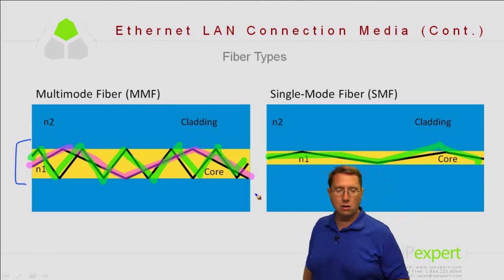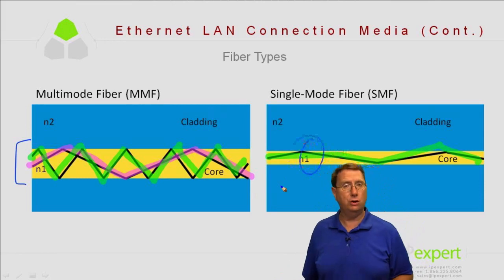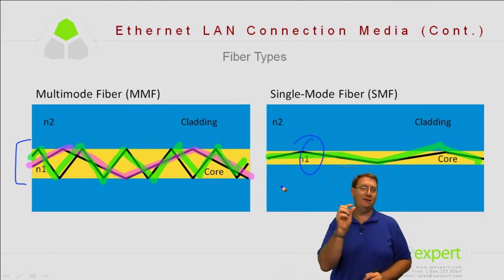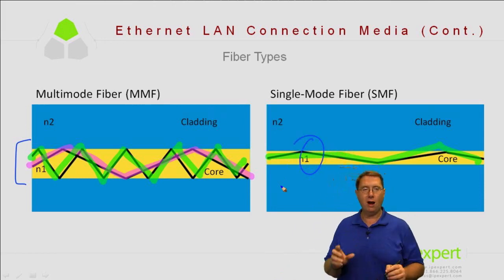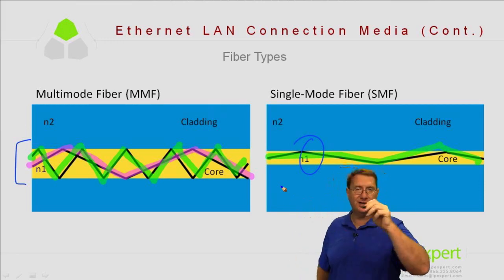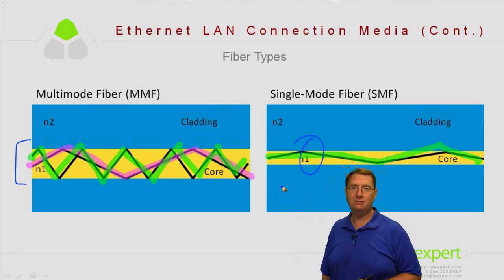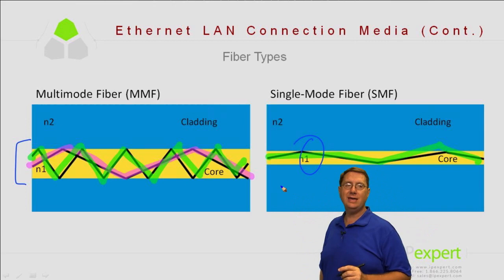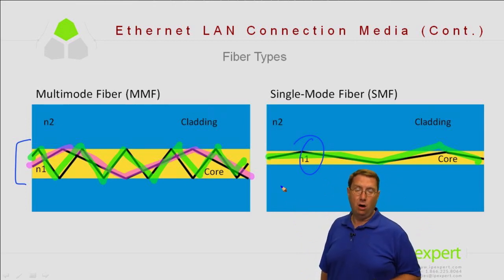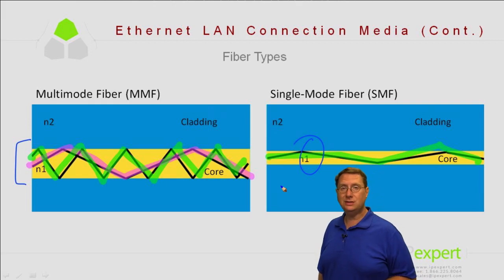Now, there's no requirement for that when we start looking at single mode fiber. So in other words, I can have a smaller conductor, therefore I'm losing less light because I have less reflection going on against the outside of the core. But when we start looking at it, I can shoot greater distances using single mode, also because I'm only carrying the one signal type.